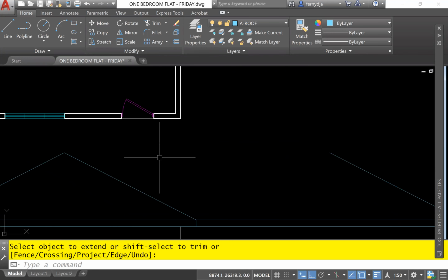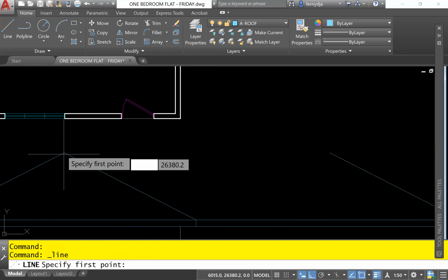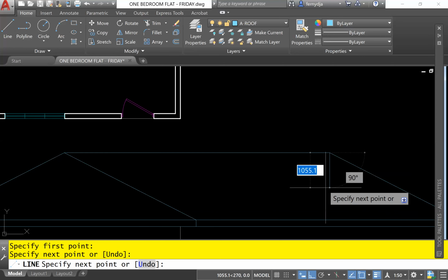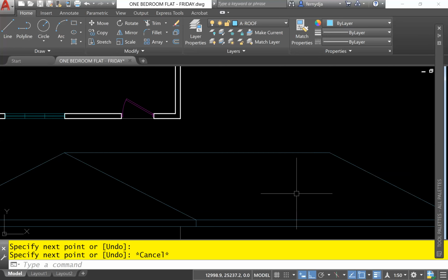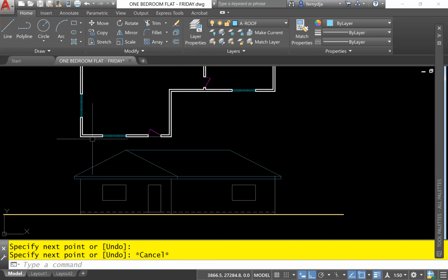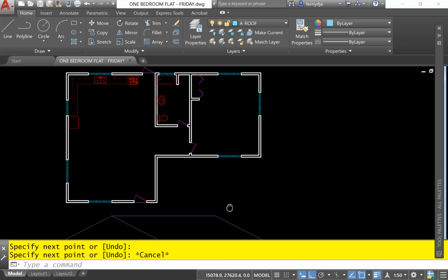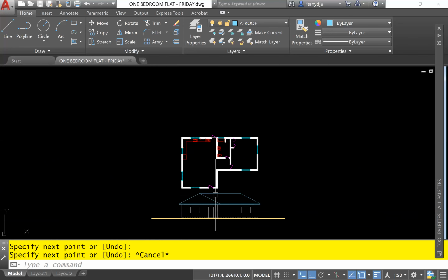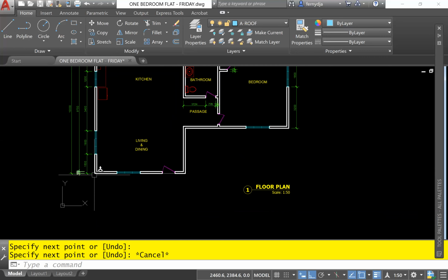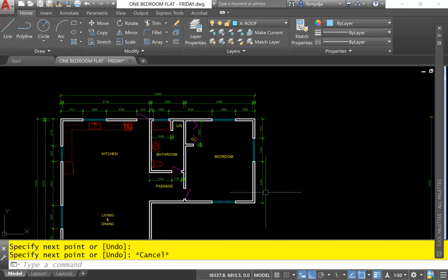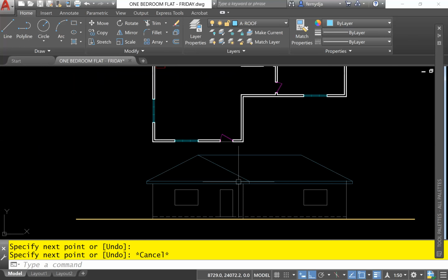And in our next segment, we are going to go in detail as to where that line will end up, but it is not correct to do something like this, to draw a line from there to there and say that is it. Because if you are doing that, which is incorrect, you are saying that the span of this part of the building is the same as the span here, which is not. We know that this part of the building is 7,000 and this part is 6,500 as overall distances. So therefore, we don't expect those two to meet at the same place, right?